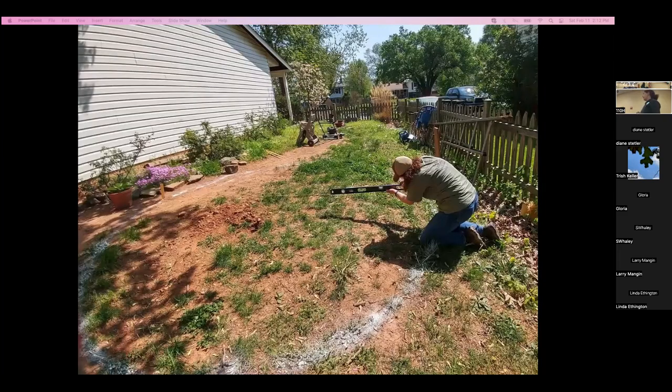All right, and now some actual pictures. So this is a rain garden that we did for a homeowner in Manassas. You can see we kind of spray painted the perimeter of that rain garden. That's me. We have the upslope stake and the downslope stake already in, and we have a rope tied between the two stakes. And I'm just making sure that rope is level as we're constructing our rain garden to make sure we meet all the dimensions we got from our calculation.